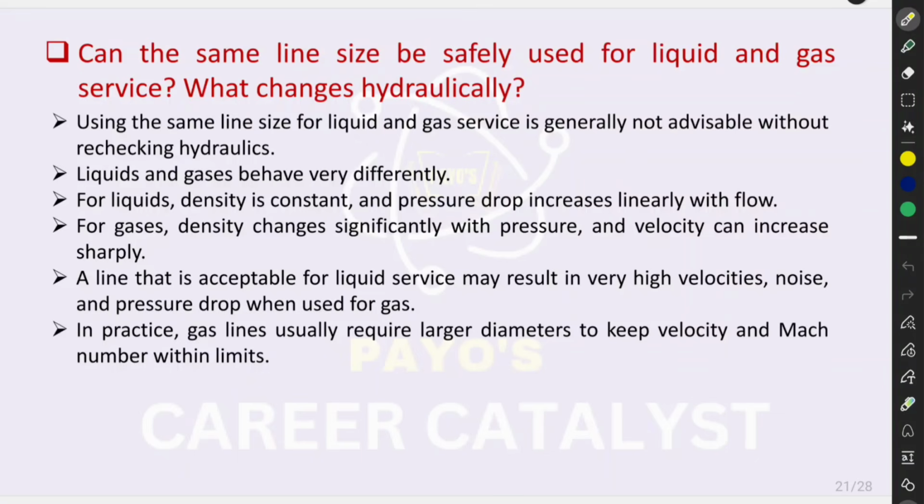Can the same line size be safely used for liquid and gas service? Using the same line size for liquids and gas service is generally not advisable without rechecking hydraulics. Liquids and gases behave very differently. For liquids, density is constant and pressure drop increases linearly with flow. For gases, density changes significantly with pressure and velocity can increase sharply.